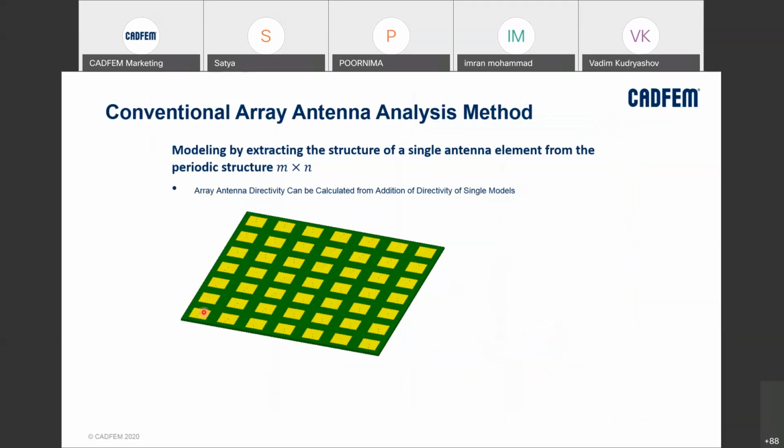and a high beam. If multiple signals are there, then due to constructive interference, it is going to bring out a very highly directive beam. And depending on the interference and the phase at the different devices, the beam can be tilted.